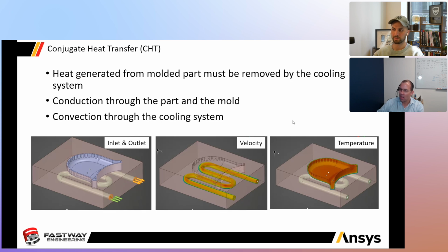Now, in real life, in the molding process, what happens is I bring in a molten polymer, and then it's solidified. So the initial temperature on this mold is going to be whatever the melting temperature is of that. We're not getting into that level of physics, right? Step one of creating a simulation, no matter what it's for, is understanding, can I simplify the physics without reducing accuracy? So I'm not going with the full phase change, melting to solidification and the amount of energy that takes. We're simplifying it just a little bit.